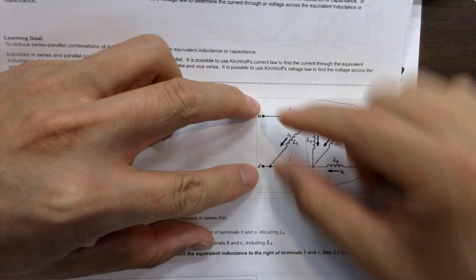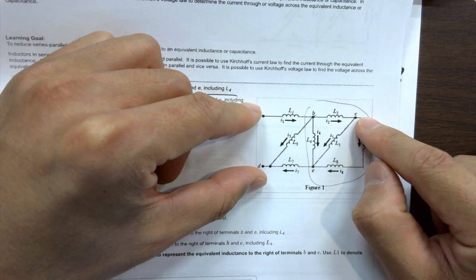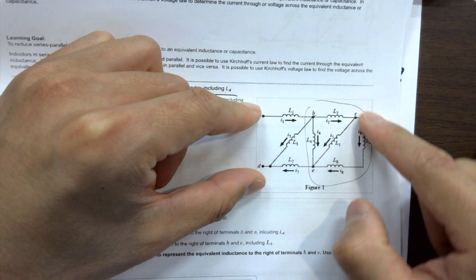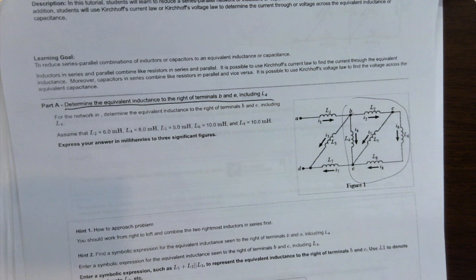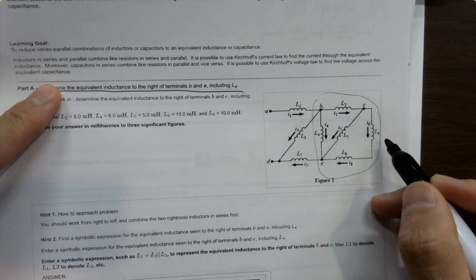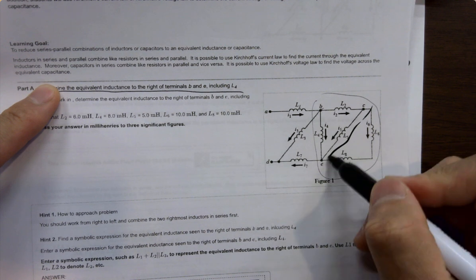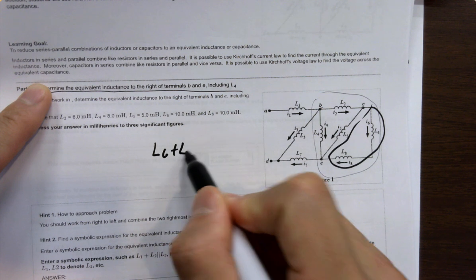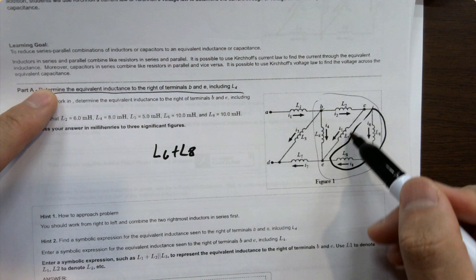What's happening is you've got the two nodes, you just assume there's a current flowing into it, right? At the end here, you've got this getting split into two branches. You've got two here, they are basically in series. I'll just write it down for you. You couldn't see the label, but I'll tell you this is L6 and this is L8. So for these two inductors, you're getting L6 plus L8, right? And those two inductors are in parallel with L5.